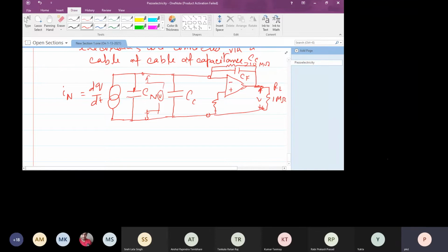So now this voltage, if we measure, because of this cable capacitance, which is of some value, a typical value as given in Bentley's book, like this one is 1600 picofarad, and compared to this one is like 600 picofarad.